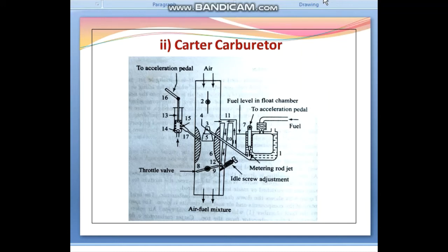The low-speed jet assembly supplies gasoline to the engine at idle engine speed and up to approximately 20 km/h. The gasoline flows through a drilled passage connecting the low-speed jet chamber with the carburetor well. At idling, the gasoline is drawn through the low-speed jet and the idling port at the edge of the throttle valve. With the idling screw, the mixture for idle running can be enriched or made leaner as required.